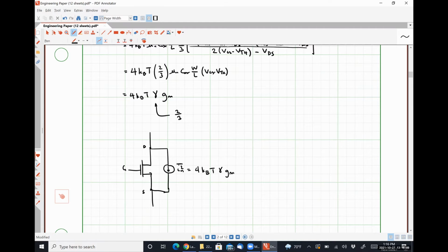So before we move on, I want to ask you guys something. What is our basic expectation of this noise? What I mean is, do we expect it to appear in our large signal model, in our small signal model, or both? Any thoughts? Just the small signal model, exactly right. The noise isn't going to push us out of our bias conditions, but when we're using transistors as amplifiers, it's potentially going to be a pain and something we have to consider, okay?